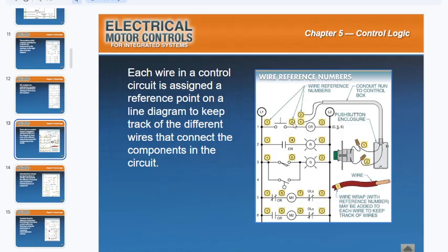And then number 2, going back up to rung 1, that wire is going from the push button only to the control relay. So this is how I find my wires. The way I find the wire is not actually go looking for the push button and looking for the CR. No. I look for number 2. If I'm worried about is there power going from the push button on rung 1 to that control relay, I'm looking for number 2.